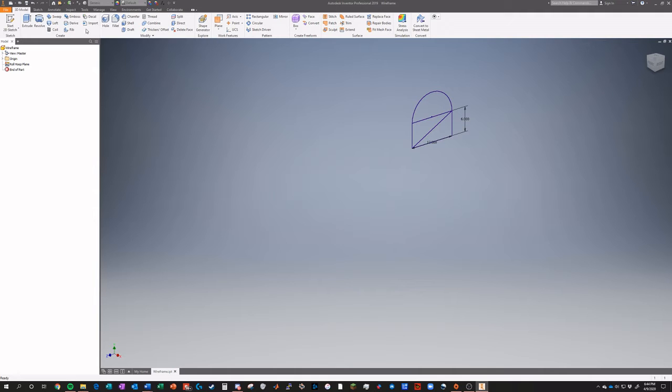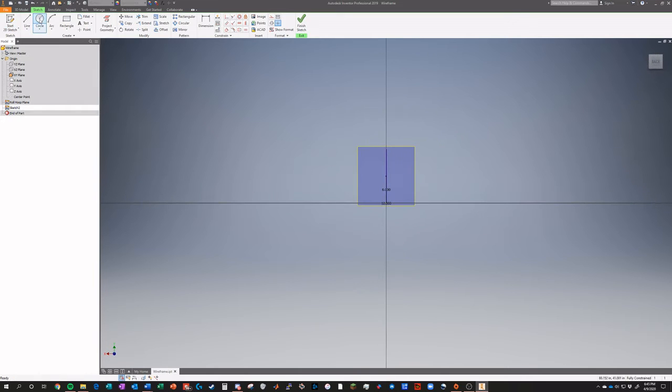So now I am going to add a plane that will have our sidebars on it. So I'm going to make this visible. And I actually want to be able to make the sidebars on another plane. So I can already make them on this plane. So if I make a sketch here, say I want to go 18 inches.